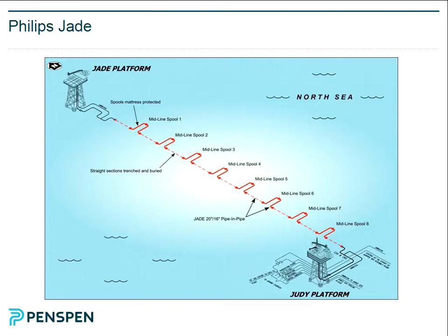I think that dealing with lateral buckling is a little bit more advanced now. And I think there was a project called SafeBuck, which was about 10 years ago, which looked at this lateral buckling phenomenon and came up with safe methods of actually allowing lateral buckling. So it's a very challenging pipeline. Definitely lots of multi-phase flow issues related to this.